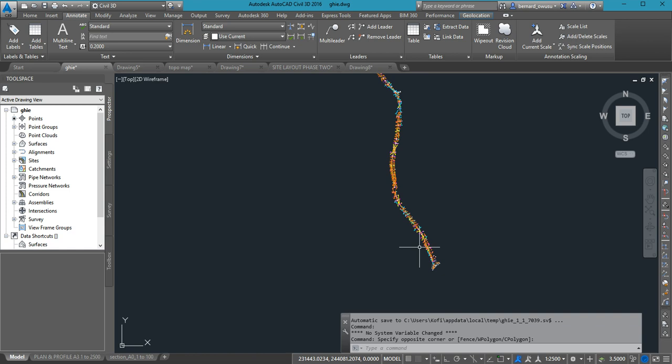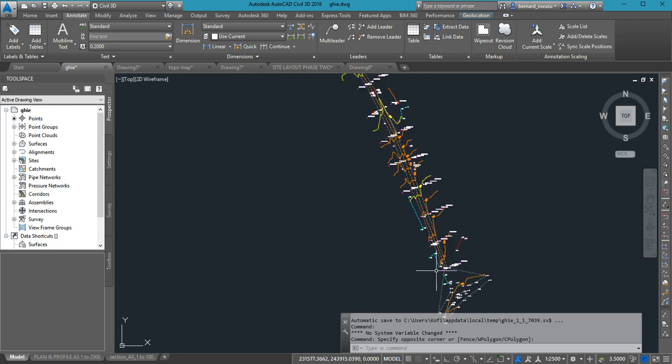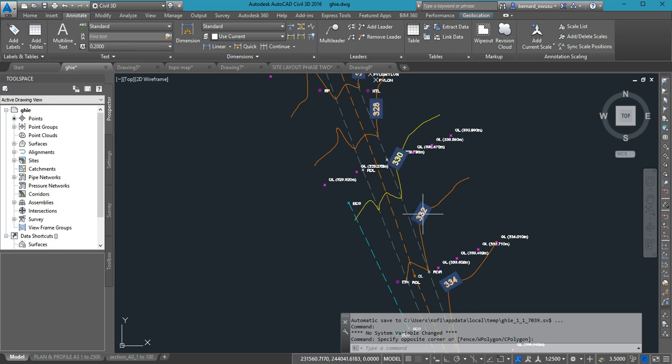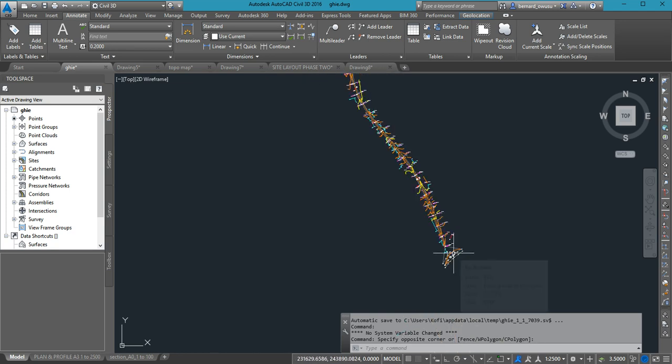So what we are going to do is define our design center line. The existing road that we have, if you remember, the surveyors also picked an existing center line, but that's not what we are going to use. We are going to define our new center line. So our new center line may not necessarily conform with the existing center line. Please, are we okay? And in putting in your center line, you want to, as much as possible, minimize property impact.